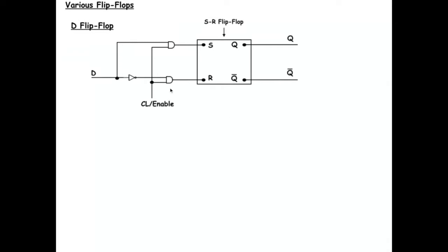Well, hold that thought. If we just had D going into S and R directly, then yeah, we would never get S and R being both 0. And why do we need to have situations when S and R are both 0? What happens when S and R are both 0? Doesn't it mean that it hasn't been turned on, there's no input?